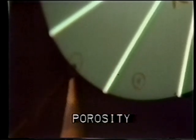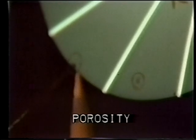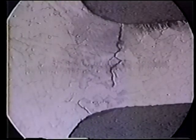Gas porosity is the presence of small holes which are formed by gas trapped within the solid metal during solidification. Generally, the porosity is round or oval and is caused by the presence of hydrogen in the molten metal. Cracks are open linear discontinuities, which can be produced in castings due to solidification stresses or mechanical damage.